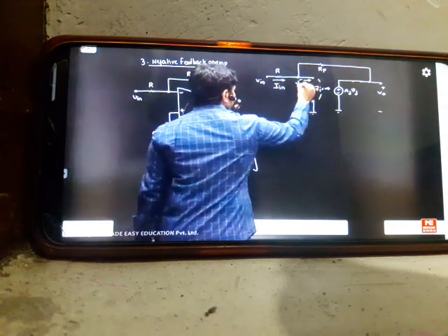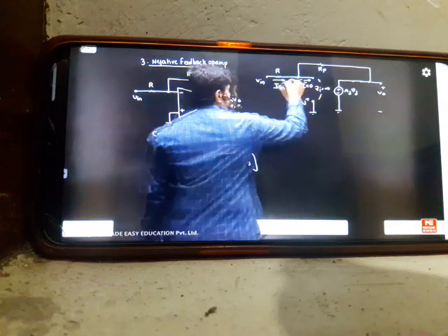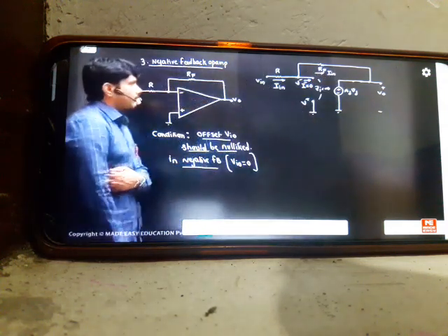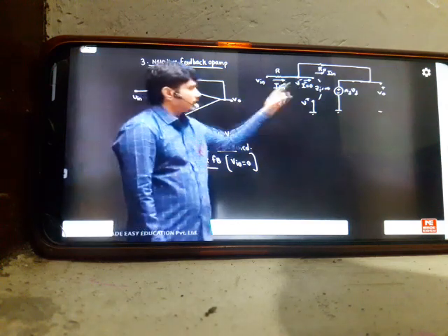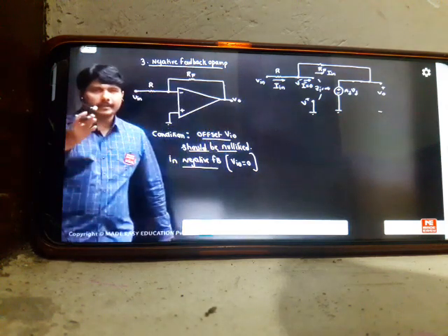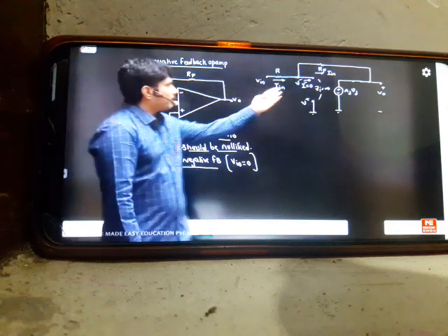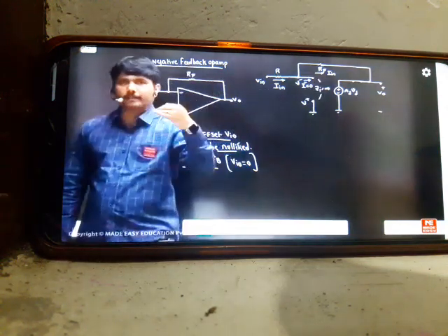But the current going to the op amp, I minus, is 0. But the same current IIN is passing to RF. So can you see that the principle has been disturbed here? Previously, the principle is that these two currents are the same for both mechanisms. In positive feedback, IN and I minus are same. In open loop also, I minus and IN are same. But in negative feedback, it has got a path to go to the output by RF. It got a path there, in negative feedback systems.